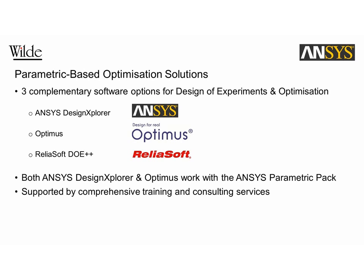So in this area, for parametric-based optimization, where we're changing design variables and trying to identify the unique or optimum combination of variables, we offer three main solutions. Firstly, ANSYS DesignXplorer, which we'll be talking about today. Optimus, which is like ANSYS DesignXplorer, but is very much a generic general-purpose optimization package, which can be used with virtually any CAE or engineering calculation software. And it also allows you to control workflow management between various software as well.